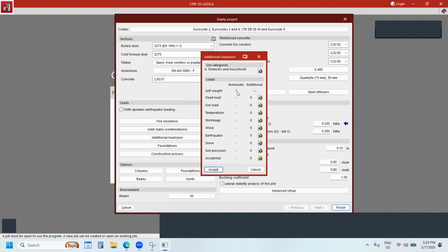Okay, so you don't need to do that. Can we not change the value for the self weight? You can apply, let's say, a dead load, and you can combine it with self-weight. Ah, okay, I see. Because self-weight will always be considered as dead load, right? Yeah, always. In some cases with our steel structure, we require calculating the self weight for the connections too. So we would prefer if we can include the self weight of the connections into this steel structure.